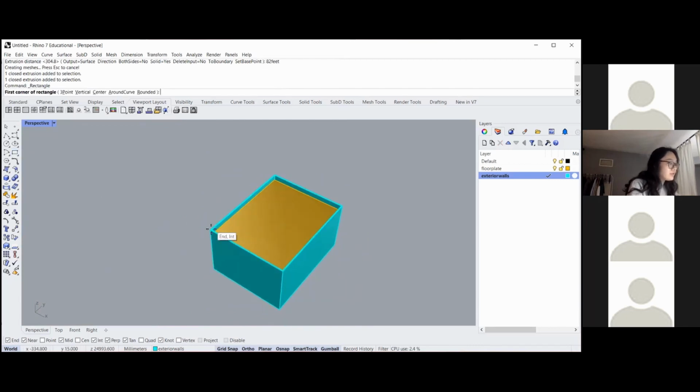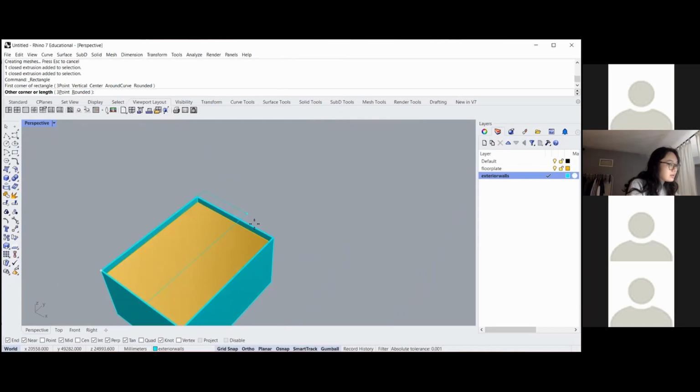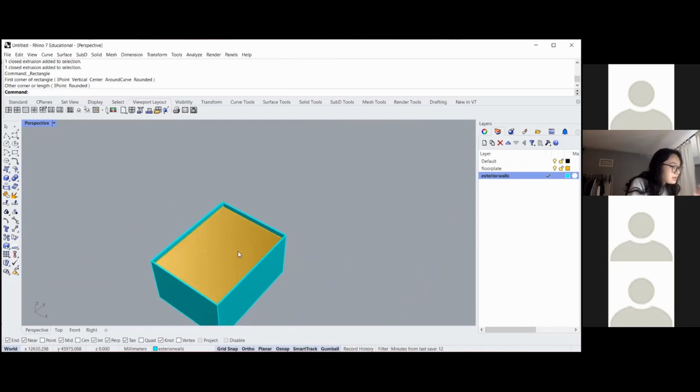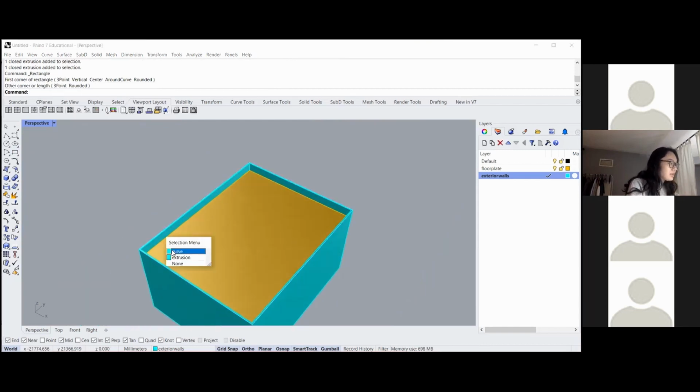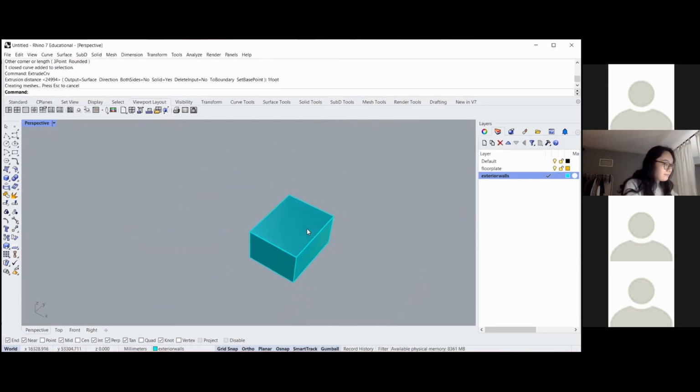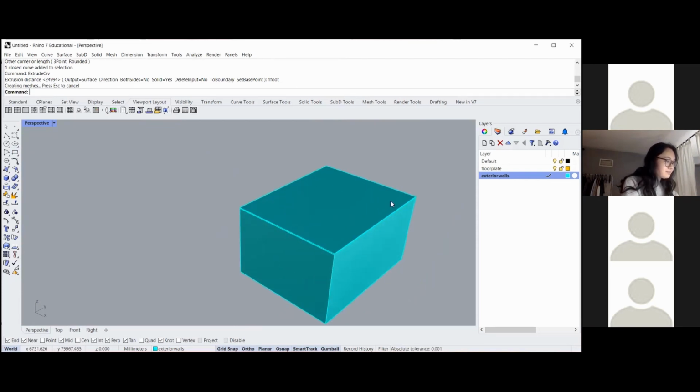And then for the roof, I'm going to create that same line outside to outside, and I'm going to extrude that one also a foot. Looks like that. Pretty simple so far. Yeah, I think there's probably a mechanical unit on the top of the building, but it's a little bit smaller, and then there are those solar panels on top. So I'm going to create the massing for that.